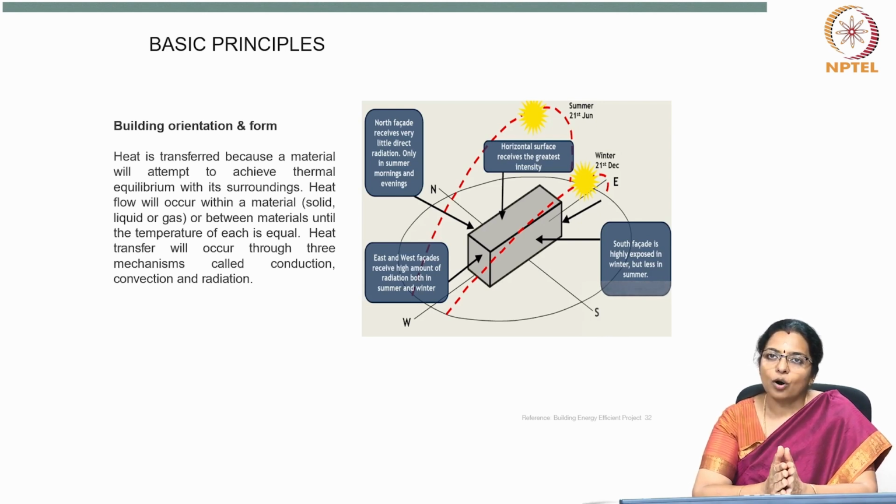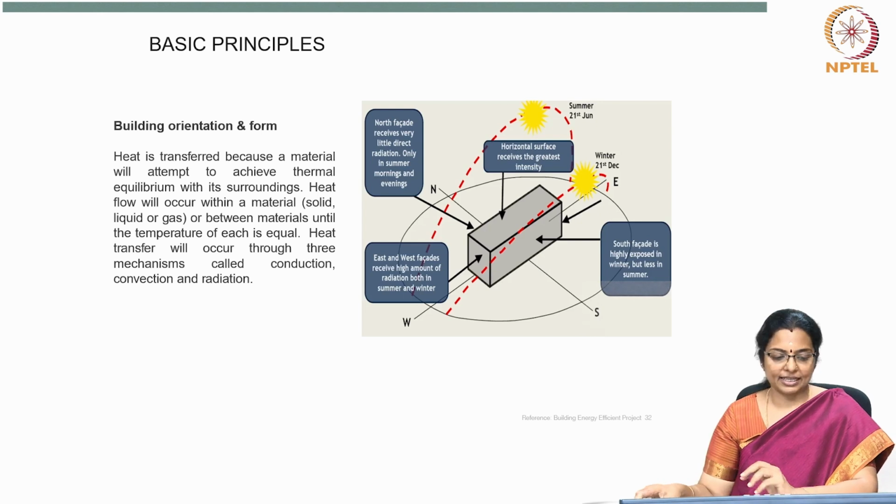Now, as the warm, humid climate zones are located near the equator, the settlement pattern should preferably be placed on southern or northern slopes. The best orientation is the longer side facing north and south directions to protect from solar radiation. However, the east and west sides should be shaded by proper shading devices.